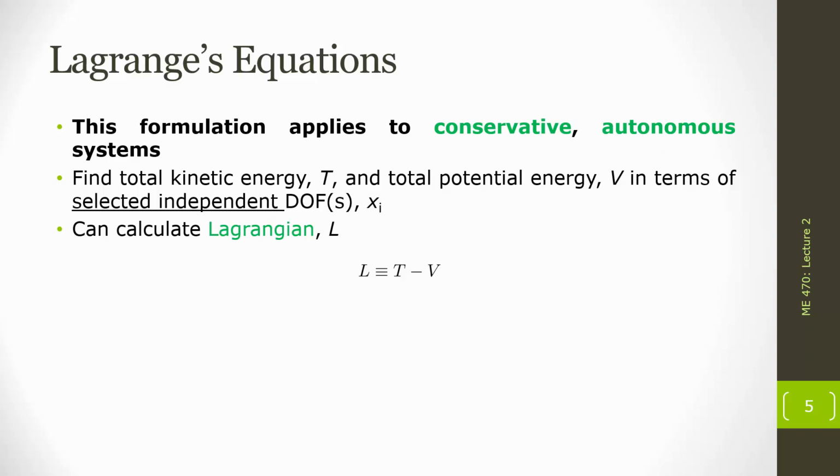I'm not going to use that technique in this class, but there's other things we can do with the Lagrangian that are useful. So really this L I'm not going to use at all after this point, but just be aware that the Lagrangian is a quantity that we can calculate using our kinetic and our potential energy. But instead, the approach I'm going to take is using the T and the V directly to derive the equation of motion in the next steps. And this will go forward as we go into non-conservative systems and as we go into forced systems as well.